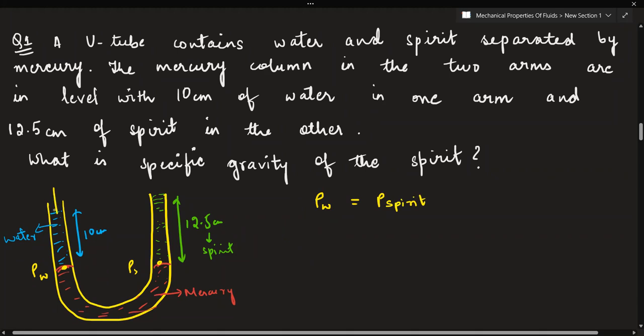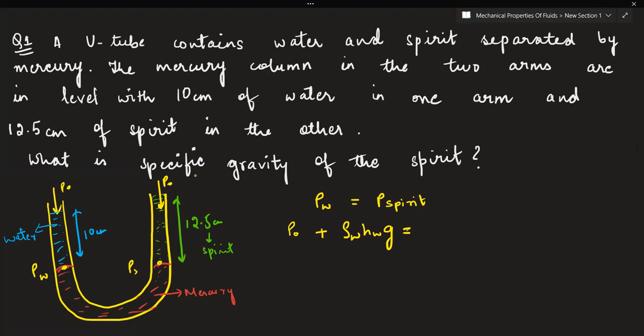Now see, atmosphere will also exhibit pressure. Pressure will be exerted by the atmosphere as well. So by considering the absolute formula for pressure, P naught, I am solving for this left hand side arm for the water, plus rho, the density of water, height of water column, and acceleration due to gravity. Is this much portion clear? I've just written the formula for the pressure exerted by the liquid column. And what is the liquid over here? Water. Yes or no? Yes, ma'am.